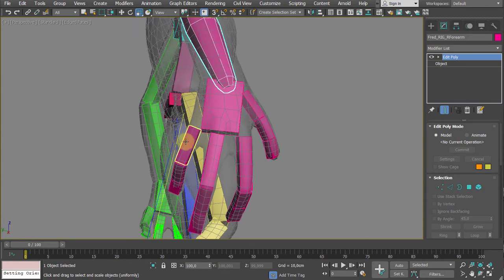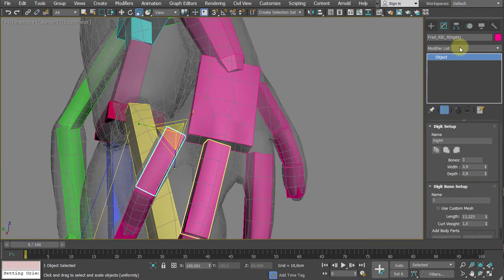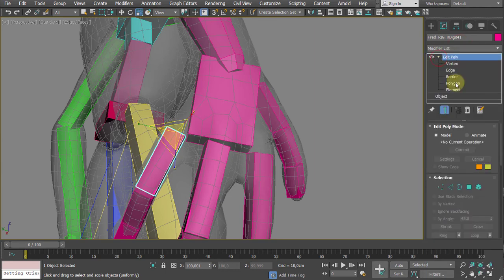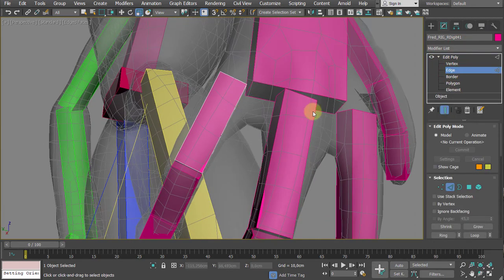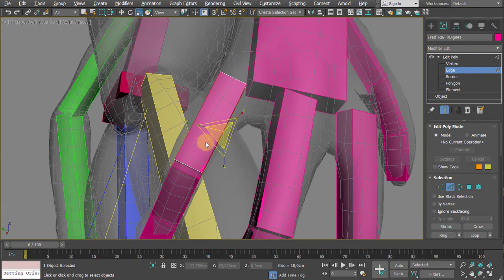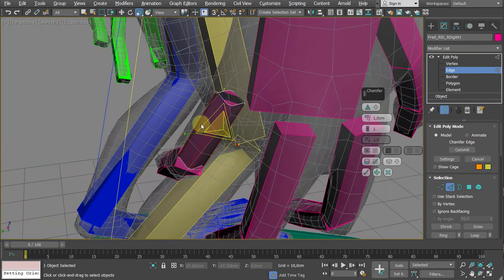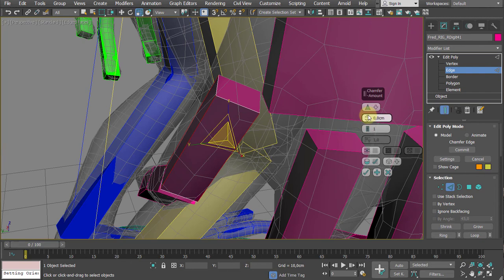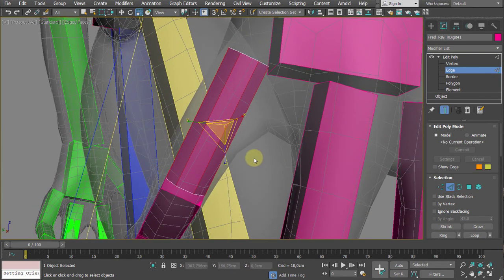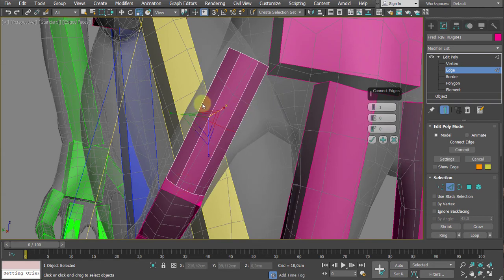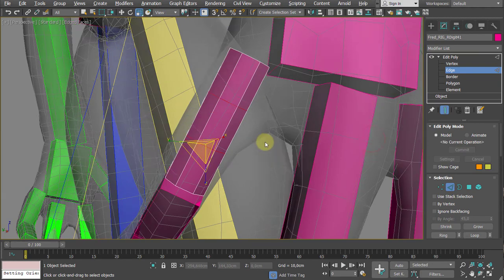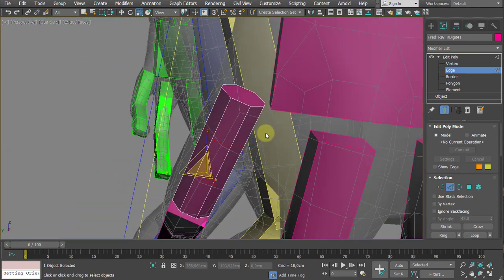make these adjustments. So for example, here's the finger, edit poly. And the typical process I like to do regarding the fingers, so all bones are selected, all edges are selected, right click, we need a chamfer, a very tiny chamfer, so let me just carefully adjust this chamfer. It's pretty hard, alright, let me accept this. We need 2 connecting edges, so instead of 1 set, I've adjusted it to 2, so now we have 2 running edges, and we need the end caps.